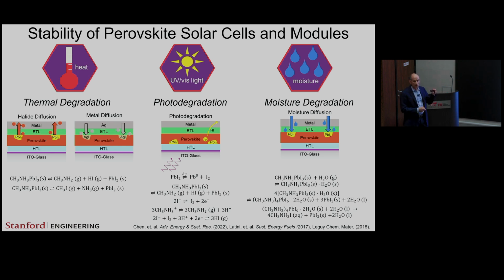It's not just the stability of the perovskite layer itself, although, of course, as you know, those layers are unstable, they're mechanically unstable. Chemically, the cations are able to migrate. In electric fields, they migrate like crazy. Worst thing you can do for a perovskite module, by the way, is run it at open circuit under full illumination. You have the highest electric fields and it basically shreds the device.